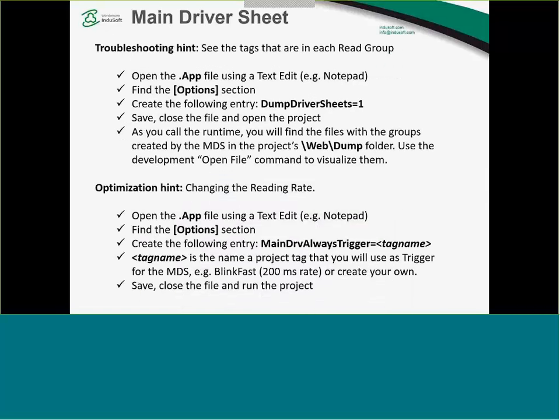So on the main driver sheet, here are some troubleshooting hints. First, you can see the groups that were created by the main driver sheets, the virtual groups. You can export them into a very similar format of the standard driver sheet. So you can go and open these files and actually see the groups. All you have to do is you open the project APP file. Every project on Web Studio has this file with this extension. Open this file using a text editor.